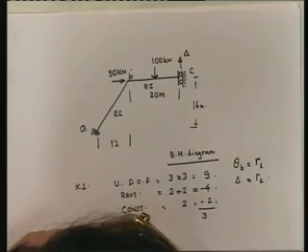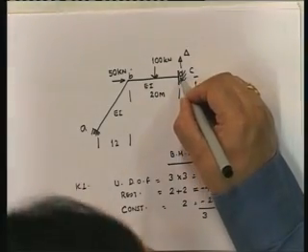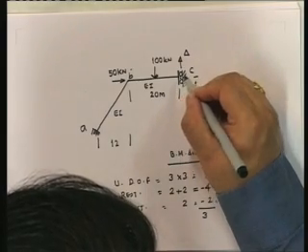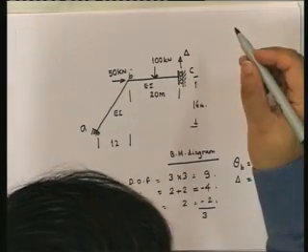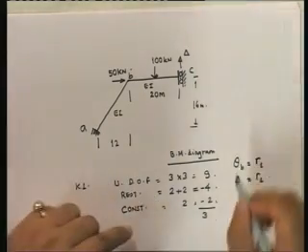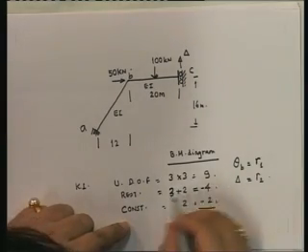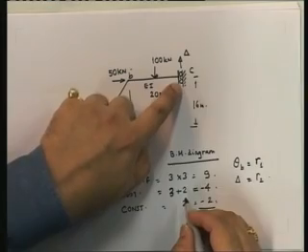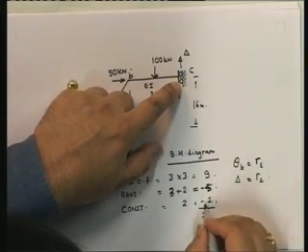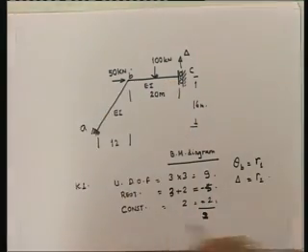Okay, let's see what happens. Suppose I stop this from going up. Okay, can this go up and down? I've made a mistake here. There's 3 restraints here and 2 restraints here. So that's 5. So 9 minus 5 minus 2 is 2 degrees of freedom. Okay.